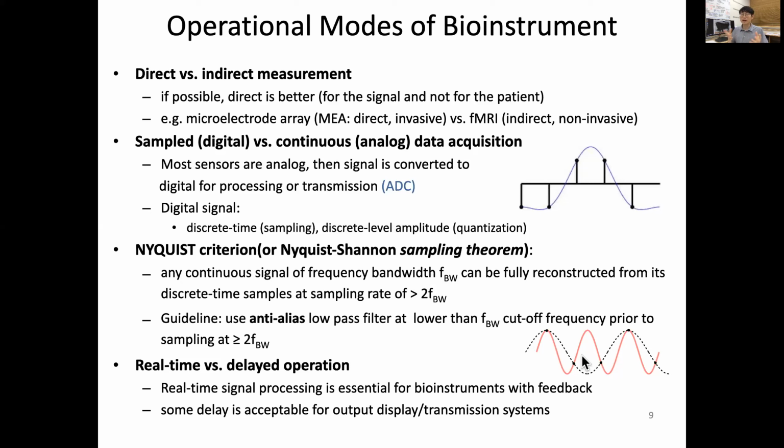So how to prevent this? We may need to condition the signal. If we know our sampling frequency Fs, then we know that we can only reliably reconstruct half of the frequency Fs. Higher than half of Fs, if we know that's not that important, it is probably better to condition the signal by putting in a low-pass filter that removes frequencies higher than half of the sampling frequency before the analog to digital conversion.